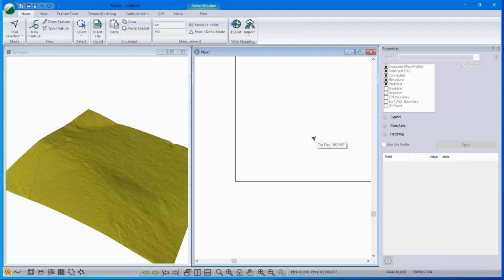Now, this is not all that difficult unless you've got a slight misalignment. If your high resolution millimeter accuracy survey data is actually a meter or half a meter or 2 meters different from the LiDAR because they're not properly referenced to each other, then it looks bad. You get a big cliff between the two surfaces.